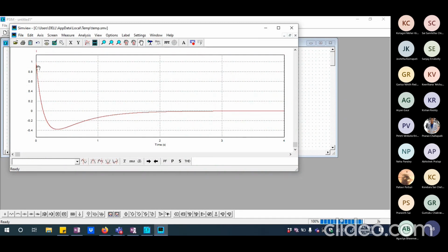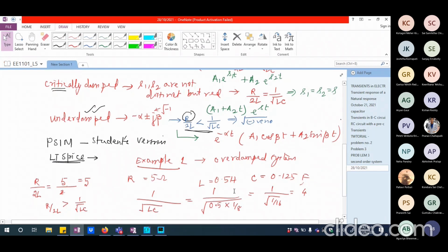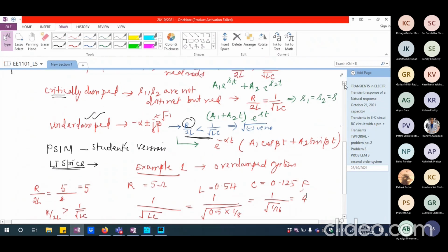See, it has initially gone with some 1 ampere of current and it has gone through an oscillation up till -4 ampere of current and it has come down to 0. The -4 ampere might have been instigated by the capacitance unless we sit and solve the entire thing, because there are 2 exponentials. Please remember what we wrote earlier. We got basically a summation of 2 exponentials, which is a1 e power s1t and a2 e power s2t.